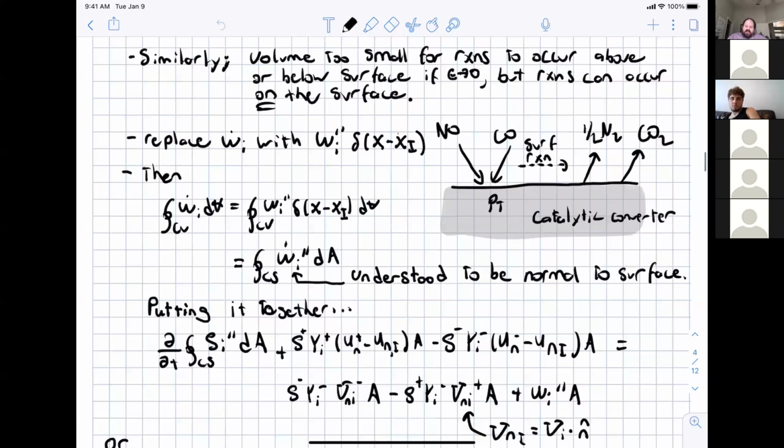Okay, now for the normal momentum, this takes care of the acceleration. Now we need to take care of the forces. And so the forces are, we have basically pressure pushing on the faces, and we have viscous stress, or some sort of normal stress due to solid mechanics, and that's defined to be positive in tension. Now there is one other force we need to consider, and that's surface tension. And surface tension exists exactly on the interface and only on the interface. So even though the area on the sides tends towards zero for our application, that does not matter. There's still surface tension there.